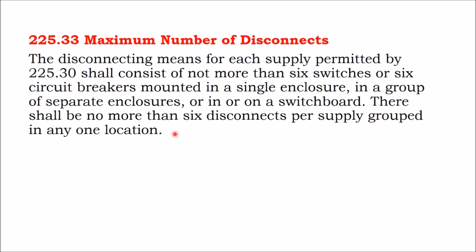And that's where if you have distribution circuits throughout a building or complex, or even coming into the property itself, if there's 6 circuits or less, they may just avoid buying a main breaker. If you buy that main breaker, no skin off your back, it might make the service panel a little bit easier to wire and service, and many electricians will order that if they have the budget to, but you don't need it to be code compliant.